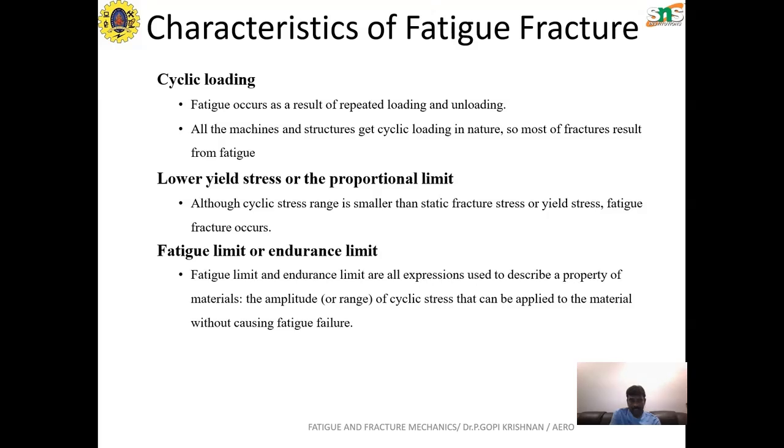There is another terminology which is termed the fatigue limit, which is also called the endurance limit. The fatigue limit or the endurance limit are the expressions used to describe a property of the material, the amplitude of cyclic stress that can be applied to the material without causing the fatigue failure.